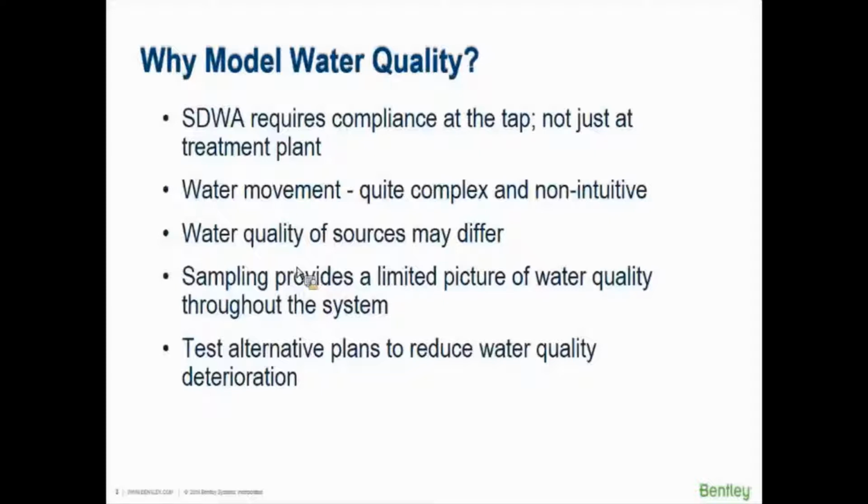As I was mentioning in an example earlier in one of the other presentations, an organization was having water quality issues at a pump station, and it turned out it was because of the pump controls. The pump station was not able to operate as well and as frequently and push out as much volume as they thought. Therefore, it was causing some water quality issues and the water quality to deteriorate in the tank.